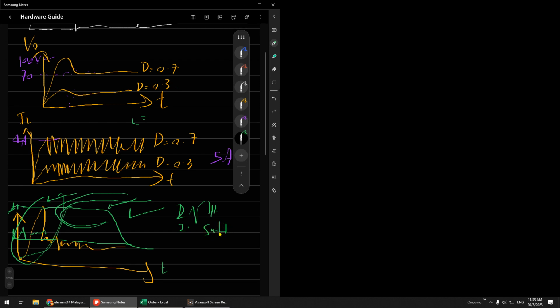For this case you cannot just put the safety factor, because inductor is quite difficult to design. The larger it is, the harder it is to design. If you use a safety factor, you can affect the design a lot. So I just suggest you add a little bit.